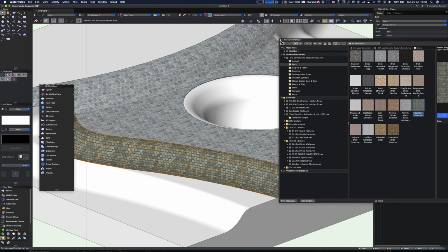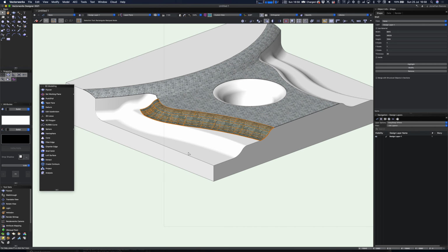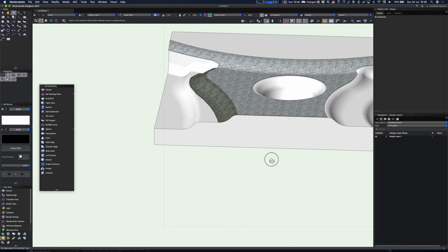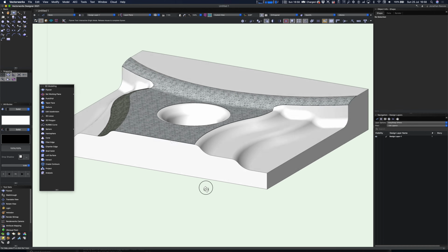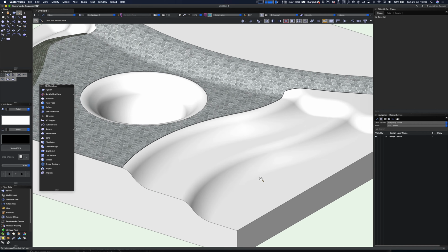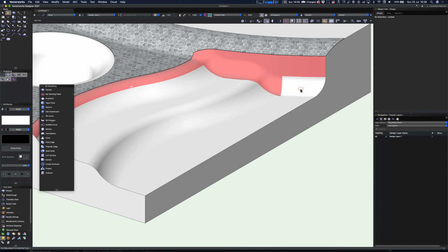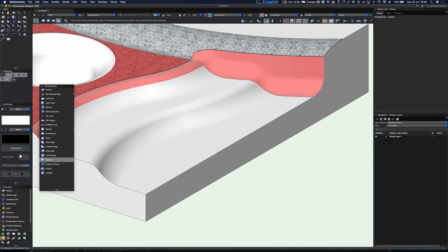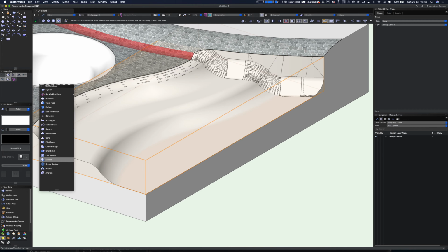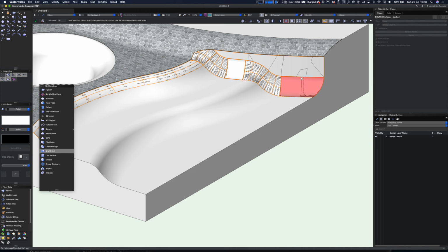We can put a nice new different sort of texture onto those. So this method of extracting surfaces, giving it a little bit of an extrusion via the shelling tool, is just a wonderful way to work on really complex curved surfaces, so that you can actually extract and basically texture up these with different materials really. And you can think this would be quite a complex process, but Vectorworks makes this super easy.